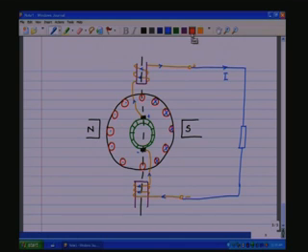Now, if you look at the nature of the winding here, we have the coil wound here and the currents flowing like this, and applying the right hand rule, we will have an MMF, an equivalent flux. We will call this one flux phi C, which is going in this direction. Likewise, here, due to the way the current is flowing here, we will have a phi C flowing in this direction.